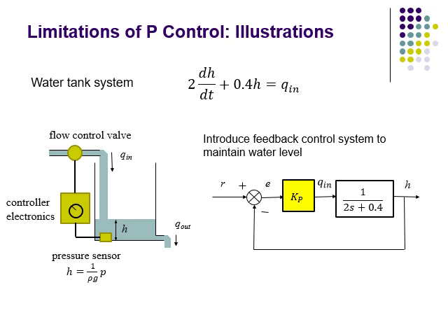In this case, if we set up the controller electronics correctly, we can get the opening of the valve to give a flow rate which is proportional to the error, right? Proportional to the difference between the reference set value for the height and the actual measured height. So this is the basic model structure for the feedback control system.